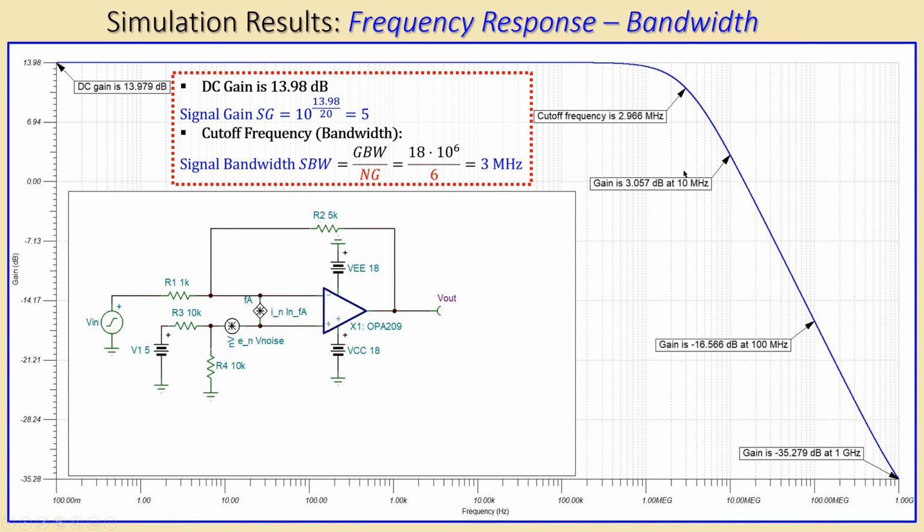If I increase this frequency 10 times, so 1 decade up, that will be 100 megahertz, and I need to go down by 20 dB. So it is 3.06 dBs, and that must then be minus 16.94 dB. It is very close to that. One is a little bit larger, so it's very close to what we actually require.